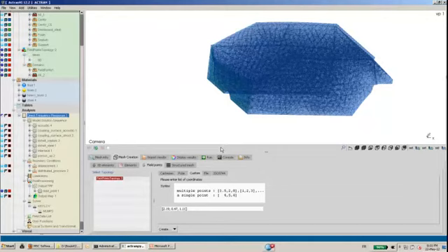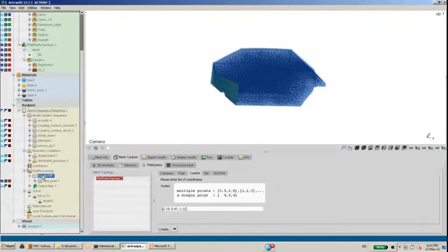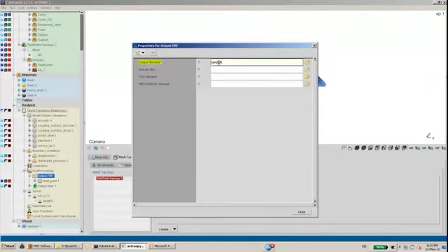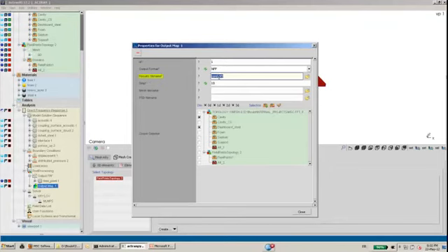But now, starting from that, I want to create the two other more simple cases, meaning first I will create the case with steel plus foam. So for that, I need to remove the septum from the analysis. It's down here. I simply press delete, and then the component is removed. And then I will simply need to change the output file names so I don't override them.